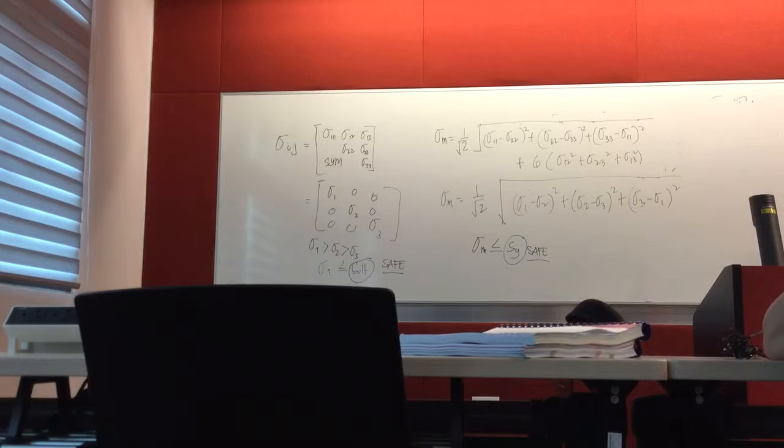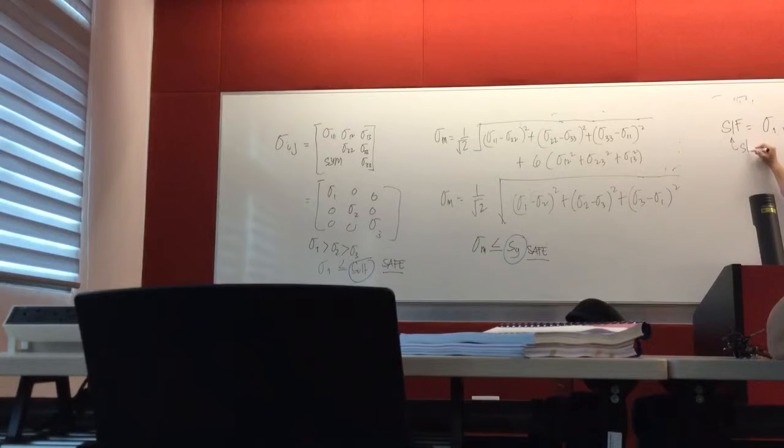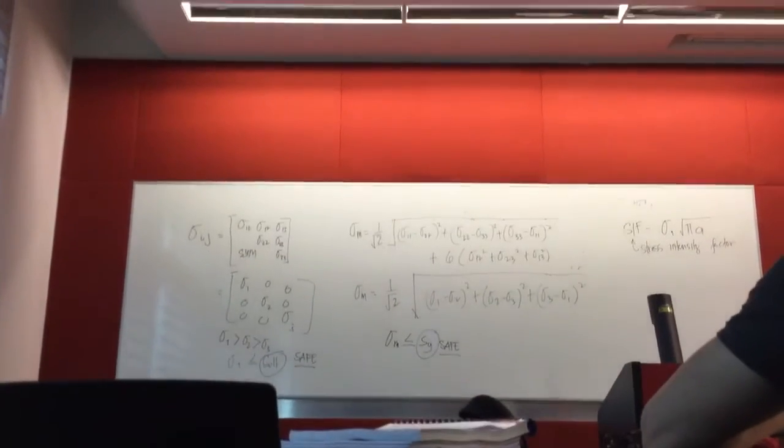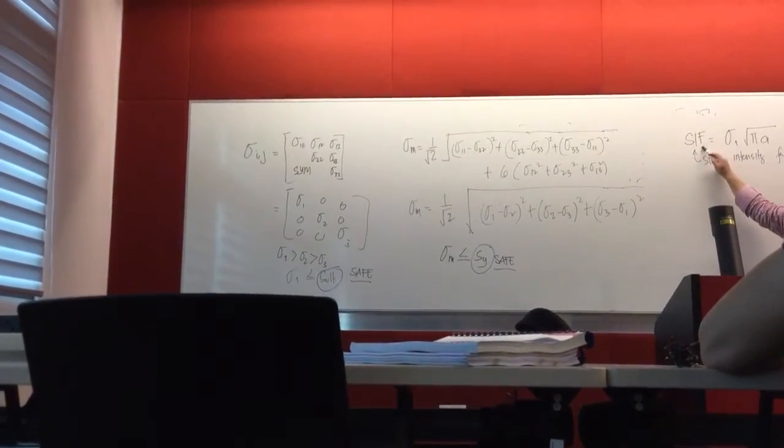Another failure criteria: the fans of fracture mechanics is now growing, and for some reason a lot of industries are adopting this failure criteria. So once you check your design, aside from doing all these steps, you also have to have a fracture mechanics failure criteria. So what is this one? This is your stress intensity factor. In fracture mechanics, this is the thing that you wanted to know.